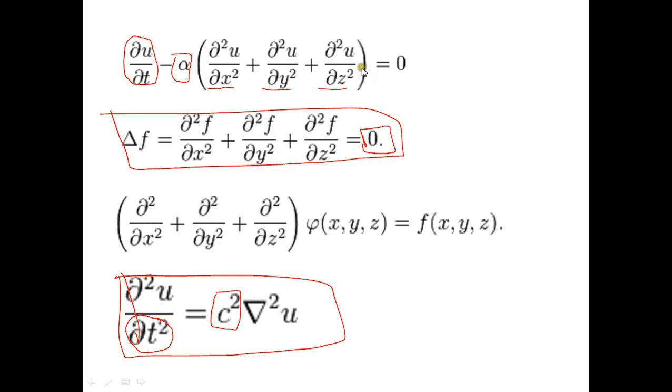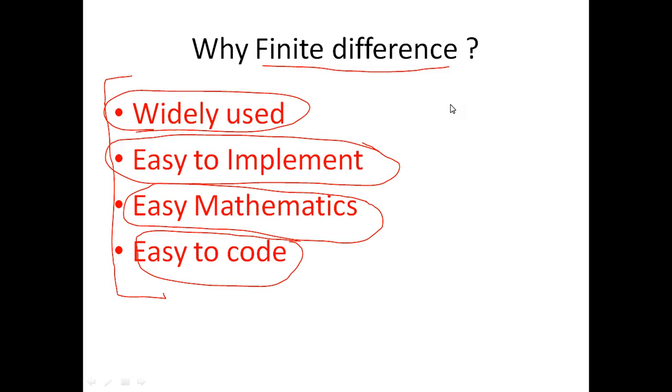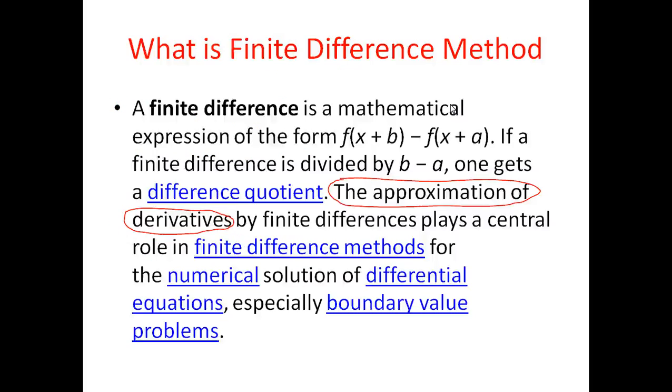We will have to transform this equation to a finite difference approximation, so that we can solve this using the finite difference methods and using the grid and discretization. So what are the steps involved in finite difference methods? Number one, at first we have to choose our domain.